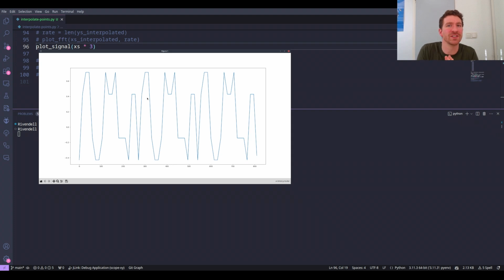So that means you need to slow this down quite a lot in order to remove the high frequency stuff and still keep these nice sharp edges. So there's even more of a trade-off you have to make there. You have to try and keep things as slow as possible, at least in this setup, right? Using this kind of digital to analog conversion method, you can't go that fast. So that's one trade-off. This is what the X position looks like.